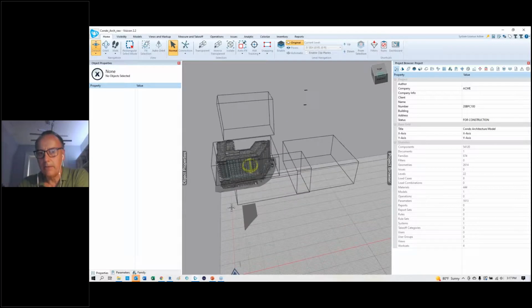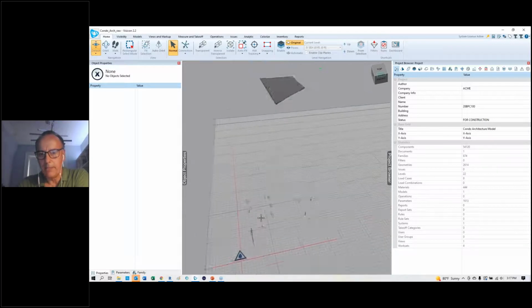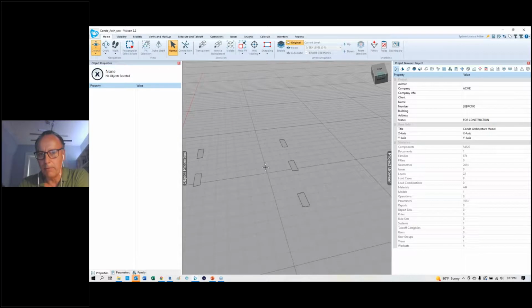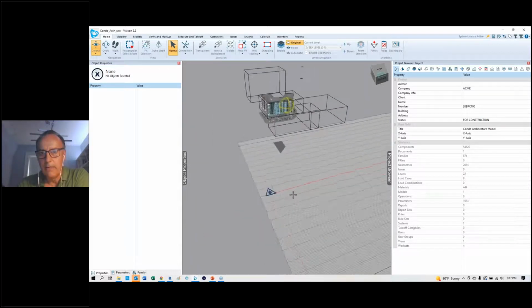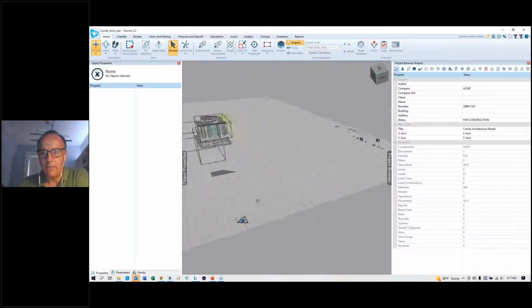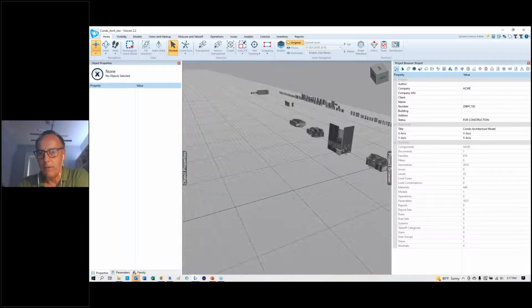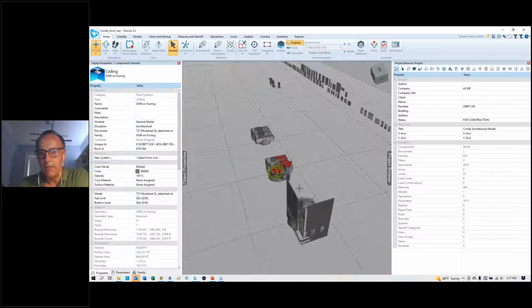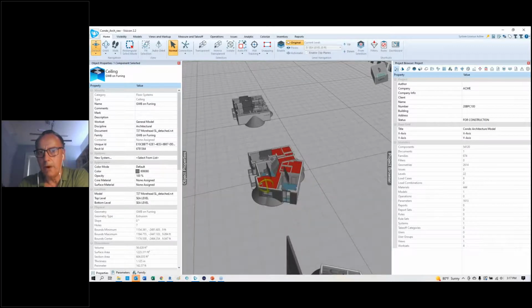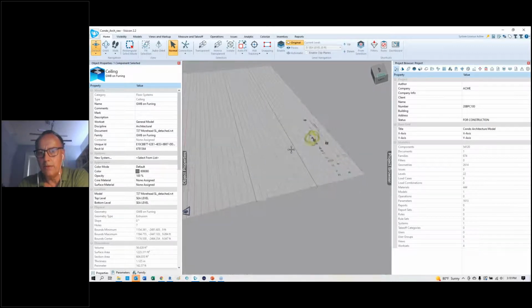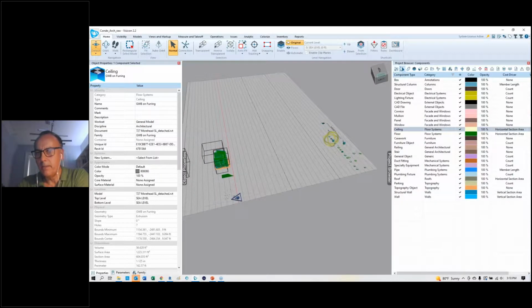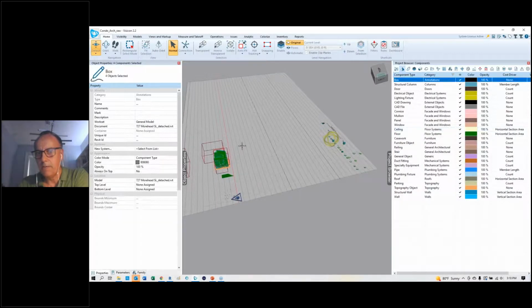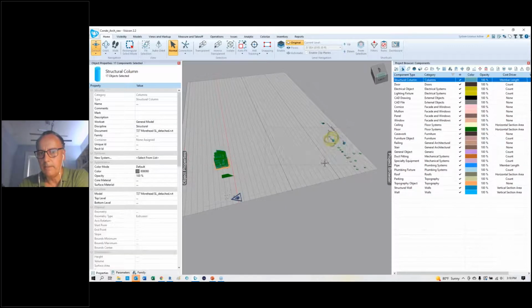This particular architectural Revit model, as you can see, has a whole bunch of sample components, or maybe not even sample, balcony areas that are down here. There's some other components out here where they're setting up sample apartment units. So we don't want any of this to interfere. It's really simple to clean it up, right? Remember, we went to this list of components. First thing I see is it still has these boxes, so I'm just going to delete those boxes.